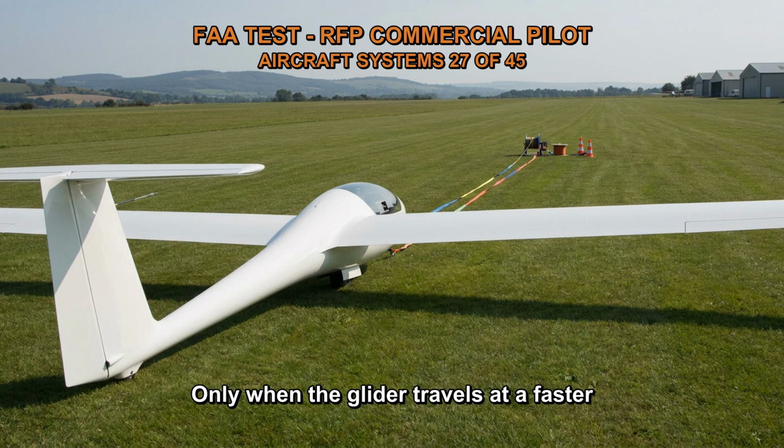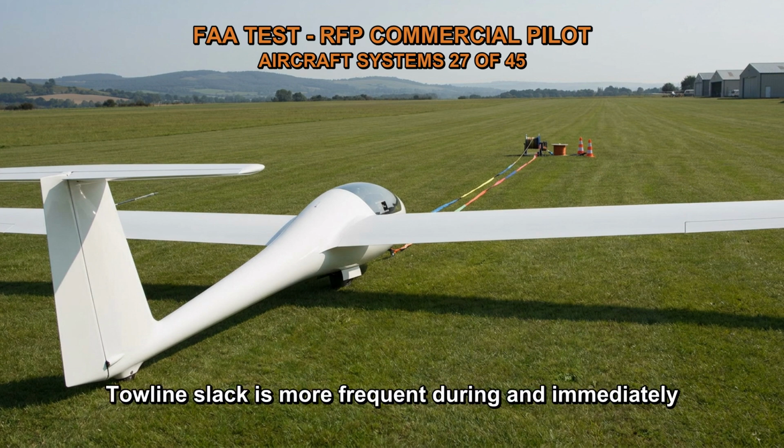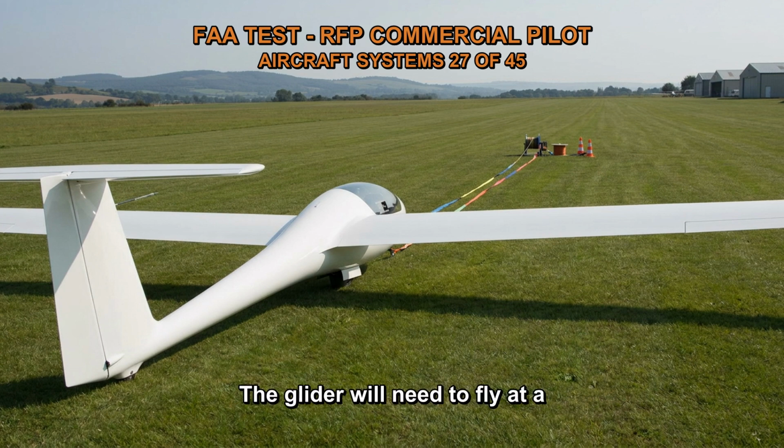Only when the glider travels at a faster speed than the tow plane can there be slack in the towline. Towline slack is more frequent during and immediately following turns. The glider will need to fly at a quicker airspeed because it is traveling farther.